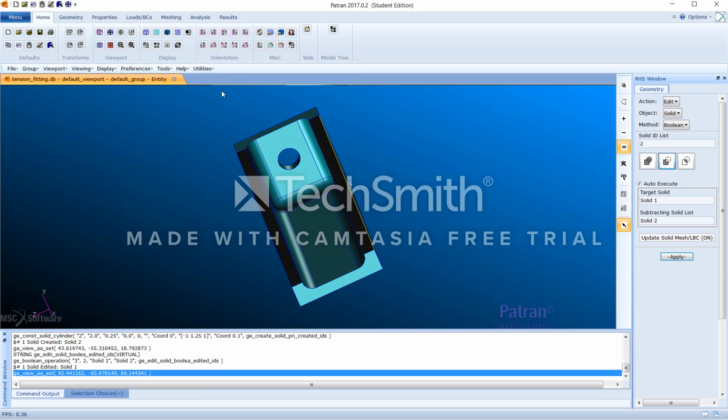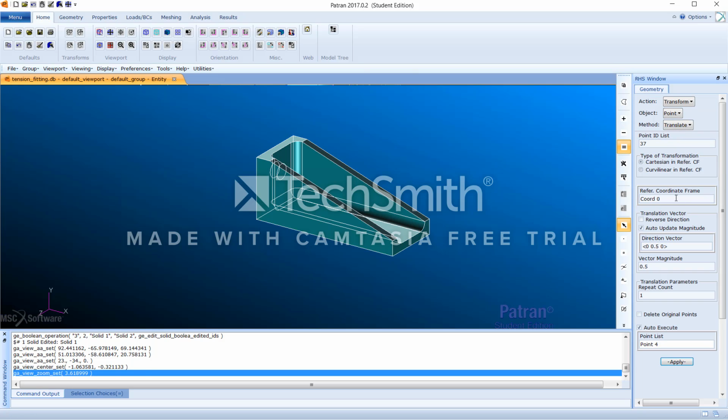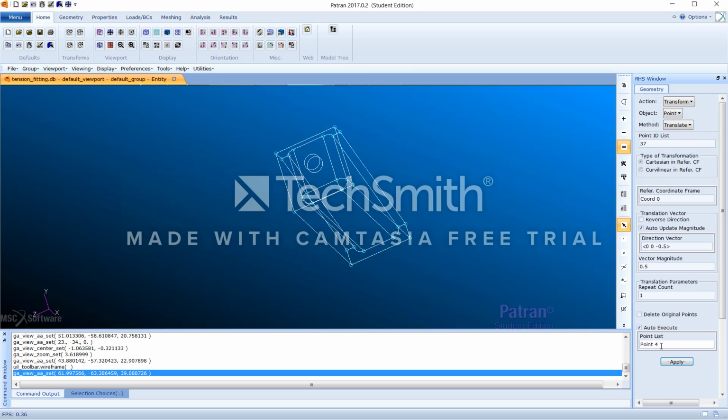Now we're going to create the points where the 3 bottom holes will be placed. Click wireframe icon, set action as transform, object as point, and method as translate. Enter 0, 0, minus 0.5 for translation vector, and select the point at the base edge of the fillet and apply it. Now for the first point, enter minus 0.7500 for translation vector. Select the new point and apply it. For the last 2 points, enter minus 1.500 for translation vector and enter 2 for repeat count and select the newest point and apply it.